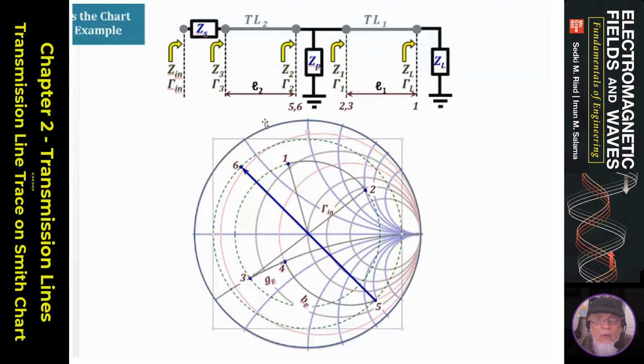Now, I need to move L2 over lambda, and again that motion is towards the generator, so I move in this direction here, and that's going to be the next one. There we go. So I move to 0.7, which is a distance L2 over lambda from 0.6. So that's the impedance at 0.7.